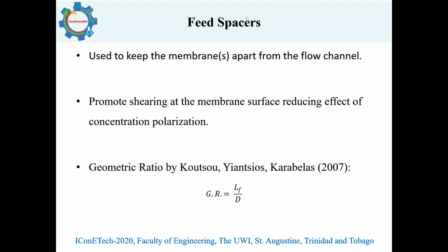Now, the thing with desalination membranes is that typically all desalination membranes make use of feed spacers. The reason for this is firstly to keep the membranes of the desalination system apart. The second is to promote shearing at the membrane surface to reduce the effects of concentration polarization.